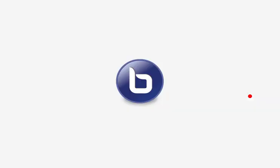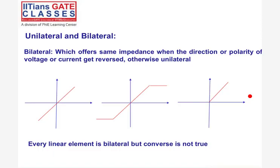Next, if you see unilateral and bilateral element, what do you mean by unilateral and bilateral? Bilateral is an element which offers the same impedance even when the direction or the polarity of voltage or current gets reversed. Otherwise, it is unilateral. Every linear element offers the same impedance if the direction or polarity gets reversed.